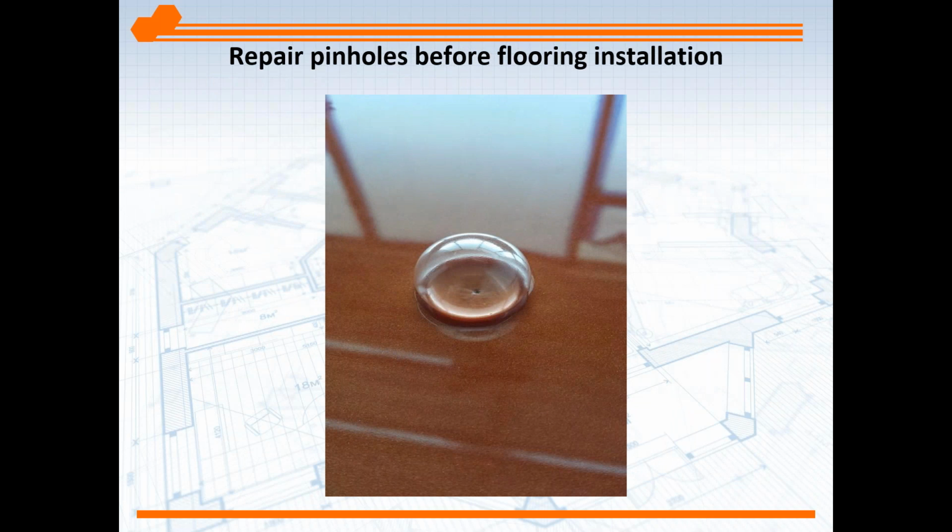When the epoxy is mixed, you could introduce air into that system that wants to escape once it's placed. Often, that epoxy membrane, as it's flowing across the surface, penetrates into the pores. As it penetrates into the pores, it pushes out air and these bubbles can form. So back rolling will close these bubbles and remove these pinholes. If ignored, they're going to be a place for moisture to come up once you install the flooring. So it's very important to make sure that there are no voids, no holidays, no pinholes prior to installing whatever floor covering you choose or specify.